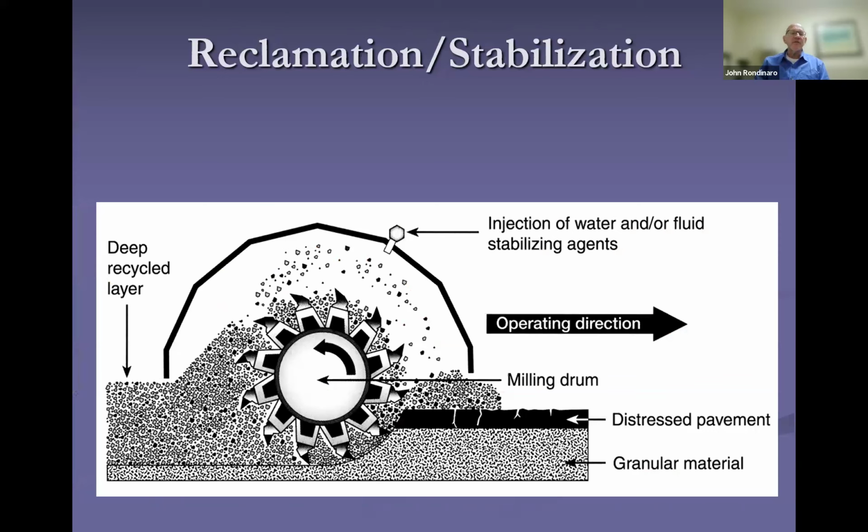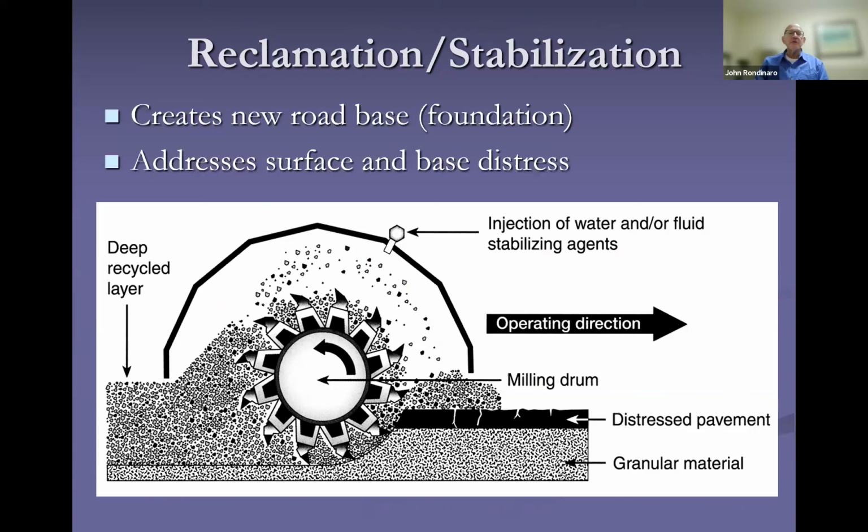And just a cutaway of the recycling and how it's grinding below, through the distressed pavement into the granular material, so that you're starting with a new foundation material. It creates a new road base, and it addresses both your surface and base distresses.